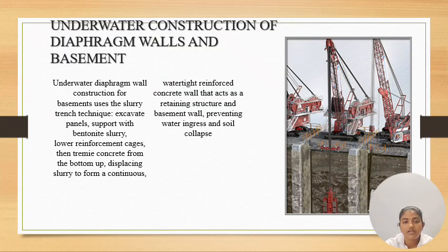And underwater construction of diaphragm walls. Underwater diaphragm wall construction uses a slurry trench technique: excavate panels, support them with a bentonite slurry, and lower the reinforcement cages.